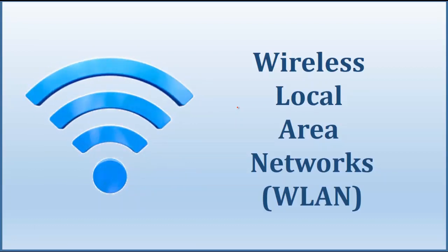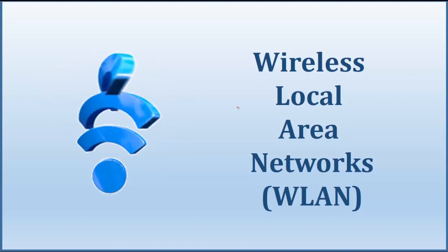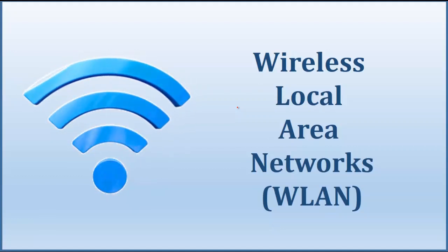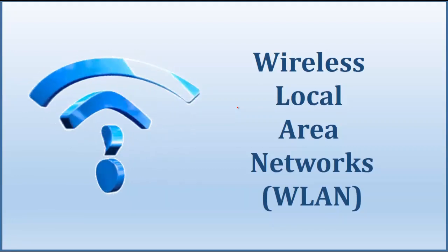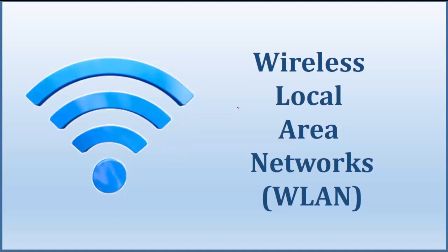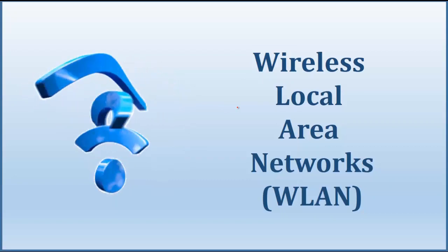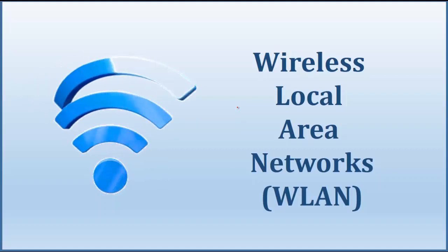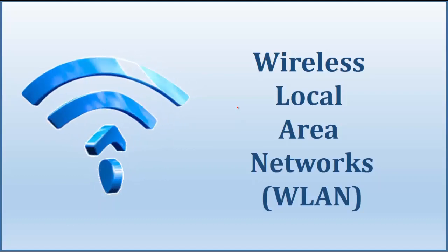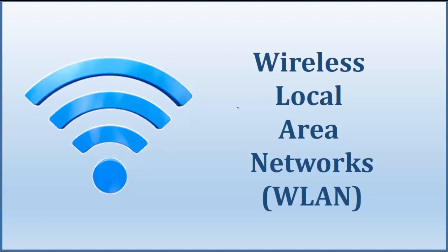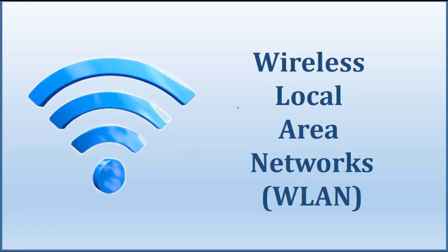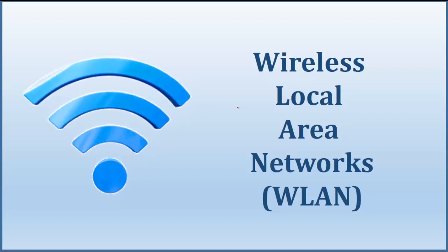Wireless LANs are designed to operate in the ISM band, or industrial, scientific, and medicine band, which is actually a radio band, and which is an unlicensed national information infrastructure band. So it is called the UNII band. In the United States, the FCC regulates this kind of radio transmission. However, the FCC does not require an end user license to use this ISM band or UNII band. So these bands could be called ISM or UNII band.